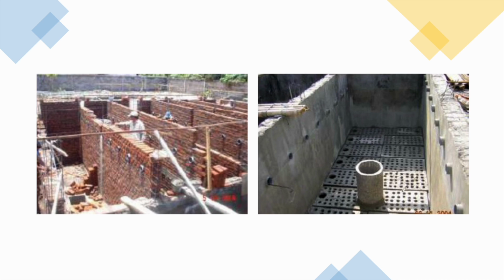And notice this slab. We have a perforated slab, and also a perforation here so that the pipe can enter, because we will have a long pipe here. Also notice we have a big opening and a concrete pipe for dislodging. When we want to dislodge, the dislodging pipe enters through this pipe.